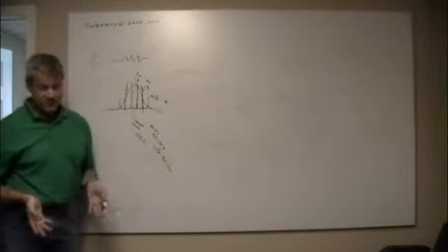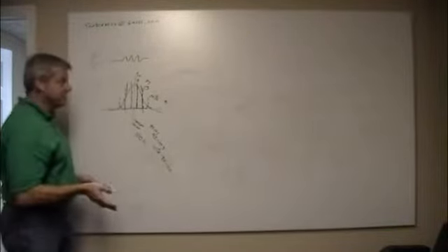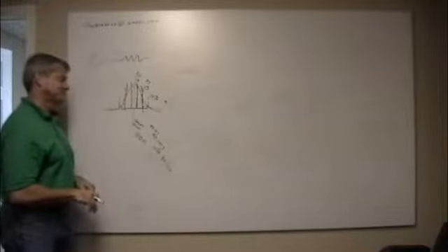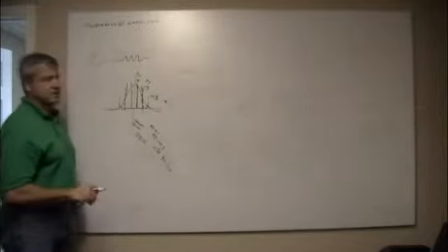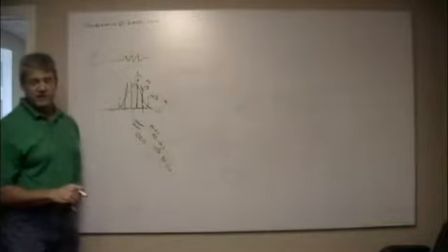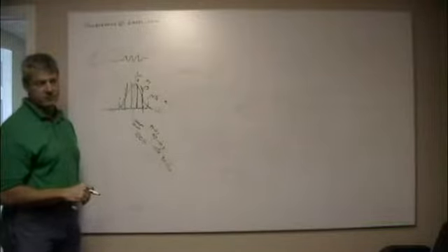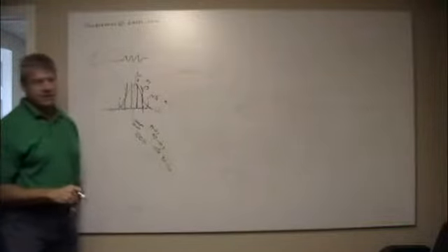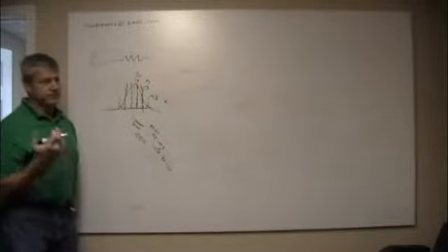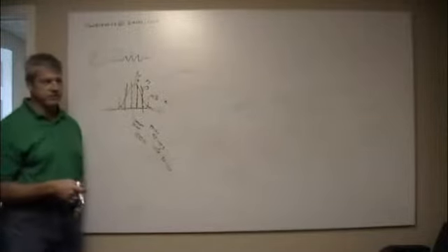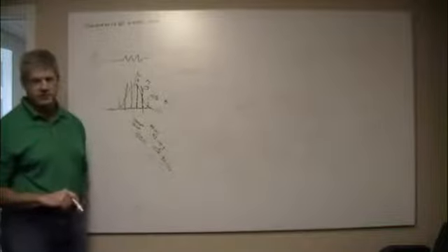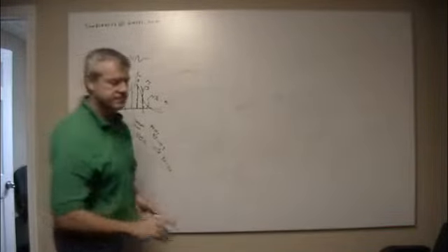So it's something to keep in mind, but these days I almost never see a 5% resistor. Everything's 2% or better, and precision resistors are easy to get, good to like 0.1% or whatever, and they're not horribly expensive.